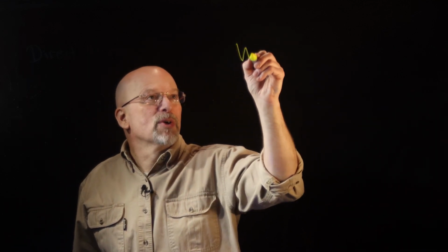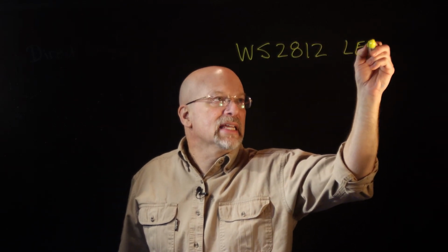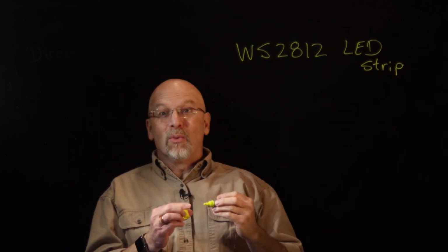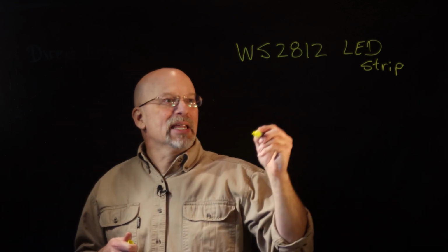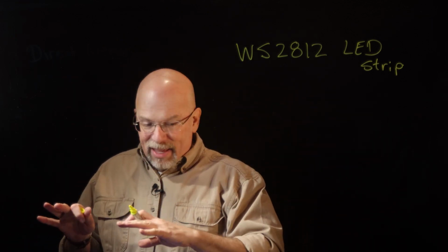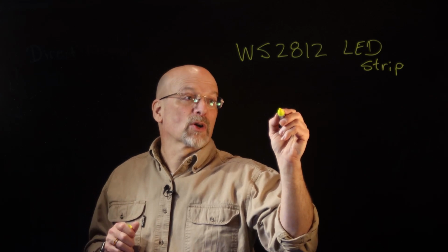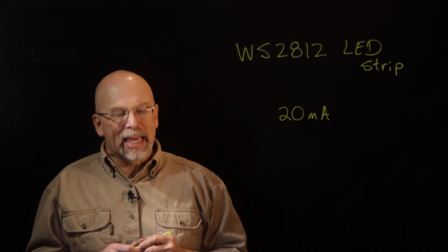Now, this particular strip is referred to as a WS2812 LED strip. As I said, each LED has 3 LEDs, so you've got a red, a green, and a blue. But each one of them requires, if it's fully on, 20 milliamps.